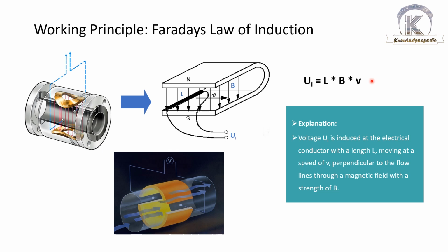So to get the volume flow, the measured velocity is multiplied with the known and fixed cross section of the measuring tube. Because of this approach, it is crucial for a reliable measurement to maintain a full pipe at all times. This is very important. I will come back to this point later on.